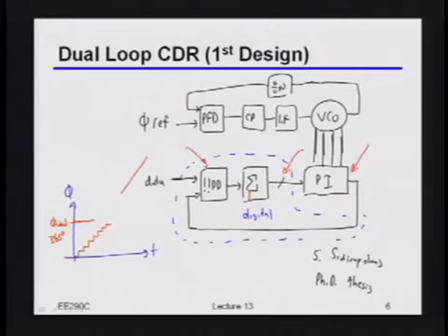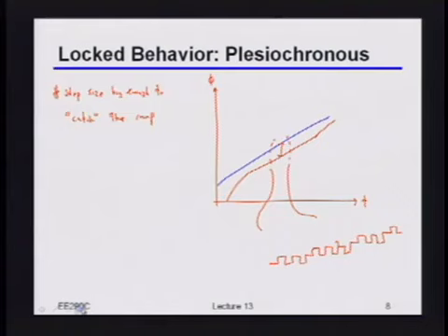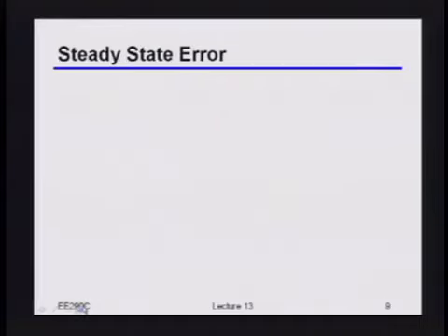So typically, you'll not really work on this full rate data, but you'll decimate it. You'll send it to some lower rate and then work on things at that lower rate. But again, we'll talk about that in more detail in 1 second. Before we do that, I did want to mention one thing, which is, as I pointed out earlier, there is indeed going to be this static phase error here. And the reason for that is fairly simple. Let's just think of this as, again, I know that this is actually a bang-bang loop with finite resolution and all that.